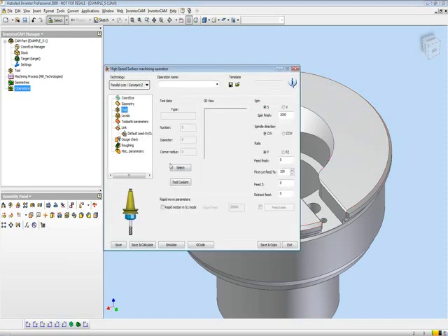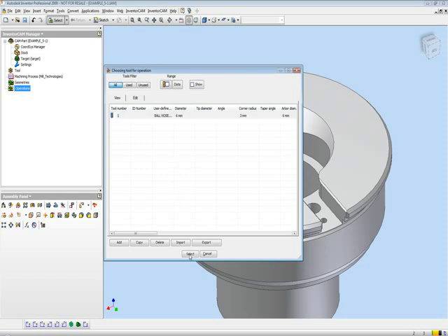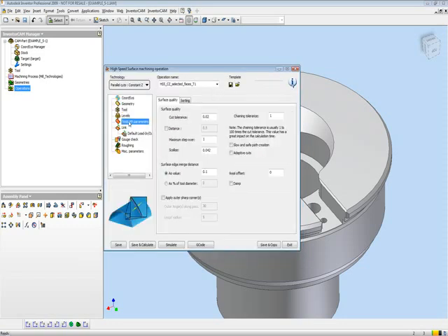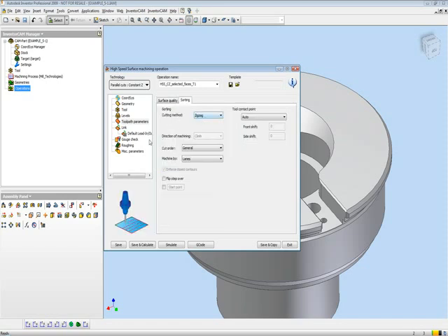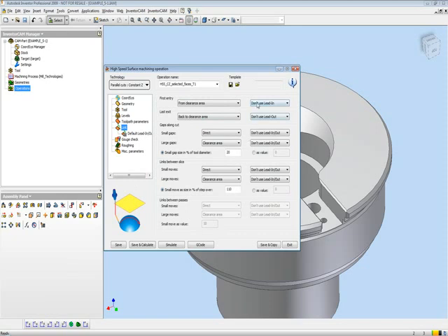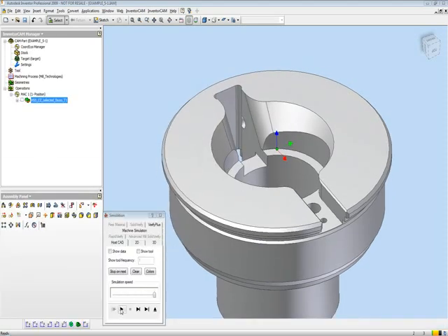The tool that I will be using will be a 6mm ball end mill, and in my Toolpath Parameters, I'll change my maximum step over to 0.5mm, leaving my sorting area as zigzag. Now, in my link, I'll be using my lead in and my lead out, and in my link between slices, I'll have that go directly from one slice to the next. Now, let's just do a quick save and calculate, and then run my simulation. You'll see that my toolpath is working exactly on that surface that I had chosen.